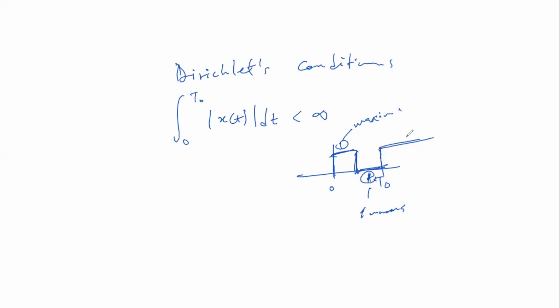And then we also talked about Parseval's theorem, which tells us that the energy content of the signal when it is in the continuous form is the same when we transform to the discrete form. So nothing affects the energy of the signal. If we try to talk about a continuous signal, and then transform that signal through sampling to a discrete signal, there is no loss of energy content.